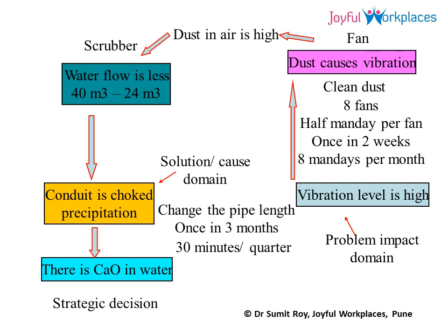And it is seen that, particularly on those days when the cleaning of the dust is done, the vibration level goes down drastically. So there was a very clear relationship between the accumulation of the dust in the FD fan and removal of the dust. Here you can see the manpower employed, and how every 2 weeks the FD fans had to be shut down, and the cleaning had to be done.